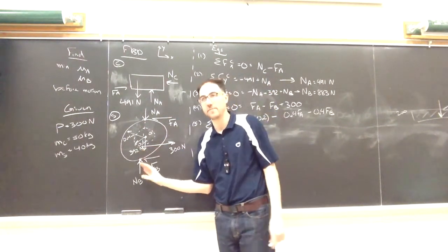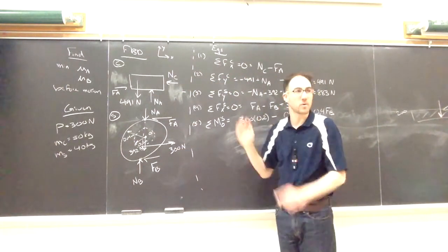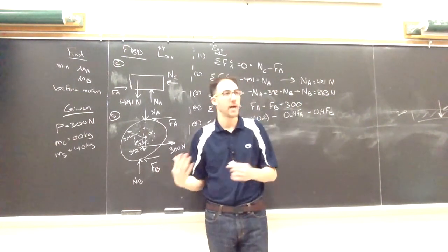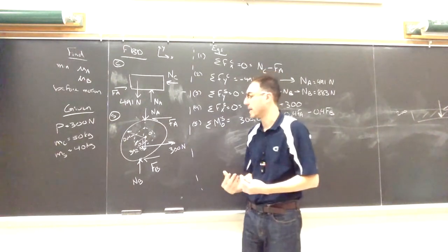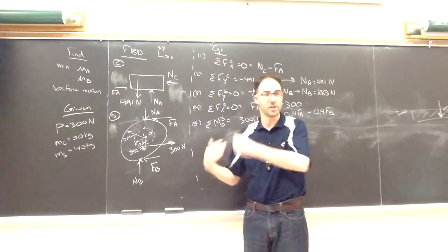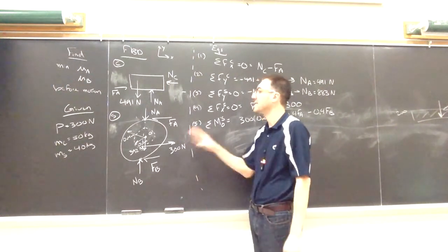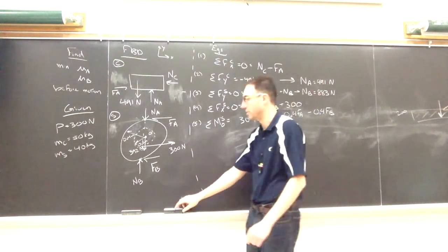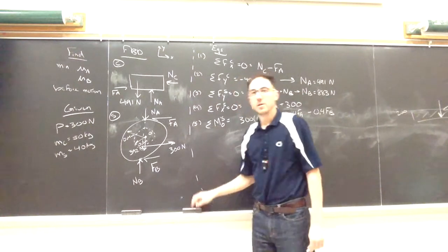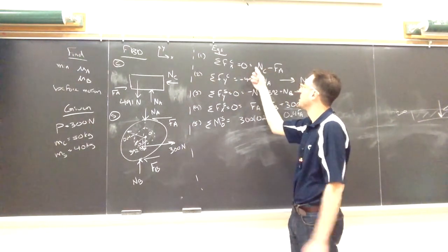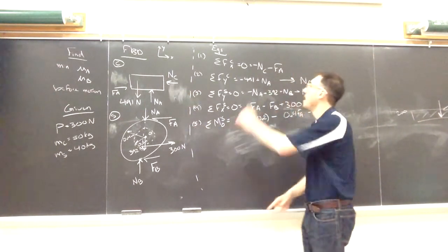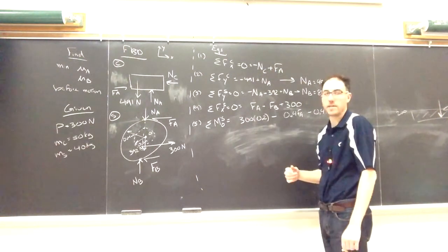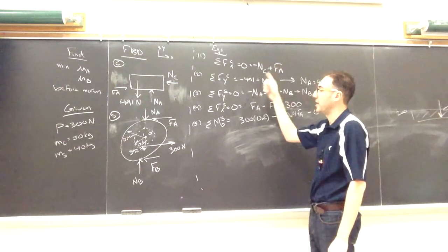Because the free body diagrams have changed, we have to go and fix our equilibrium equations to reflect that change. So there's nothing wrong with making an assumption, getting our negative friction, but unlike before where, in a pin reaction, if we got a negative number, we could just kind of march along and it would be okay, this actually changes the problem and we do need to go back, redraw it, and resolve our equilibrium equations. So going back through here, we have to look at what changes. Here, this is now pointing to the left. FA points to the right. It really doesn't change the relationship between the normal force and the friction force, but that will change.